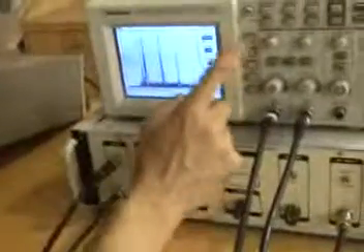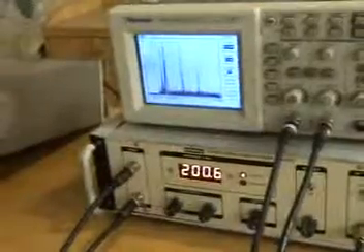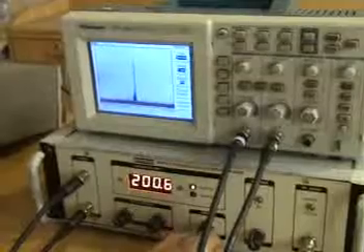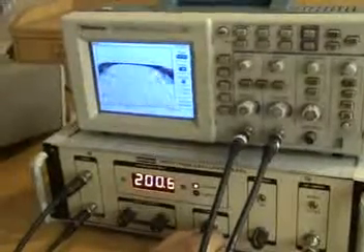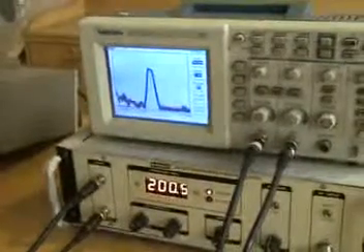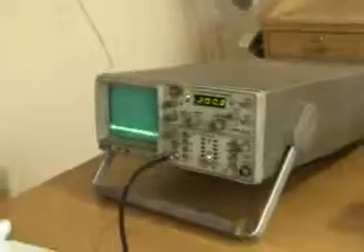Now we want to see the sensitivity of this spectrum analyzer. As you can see, we are displaying a signal strength of minus 57 dBm here. If you read, this is set at minus 10 dBm, and 4 times for this 10 dB attenuator, so the signal input is minus 57 dBm here from this signal source.